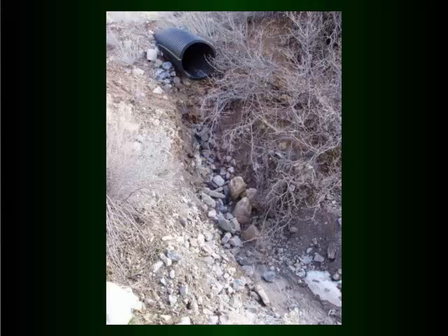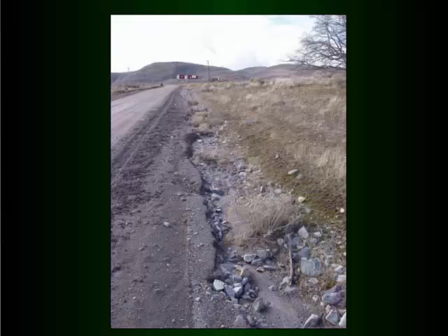On this side, I think maybe my next slide, this is the pipe that was on the right side of that thing. And it did a good job of protecting the road, but once it got off the road, there's a pretty good plunge, and you can see all the erosion right here that's undercutting. And sooner or later, it's going to affect the road because of the cutting action there. This is too much water going too far down a ditch line. You can see that it's cutting, and this probably happens seasonally.